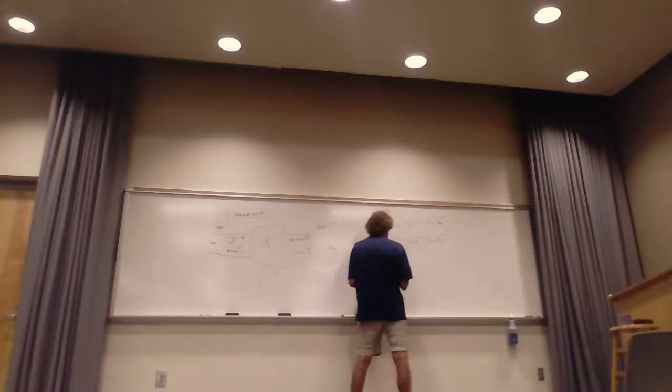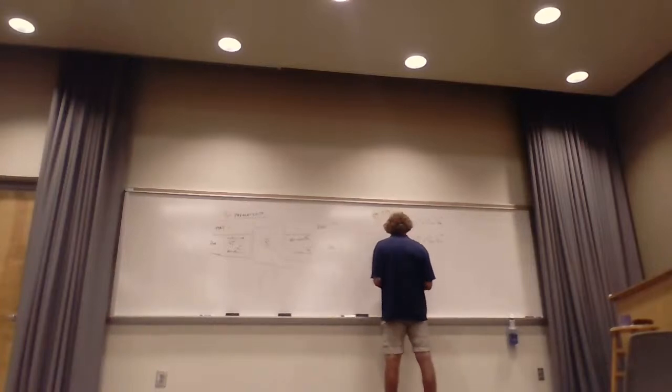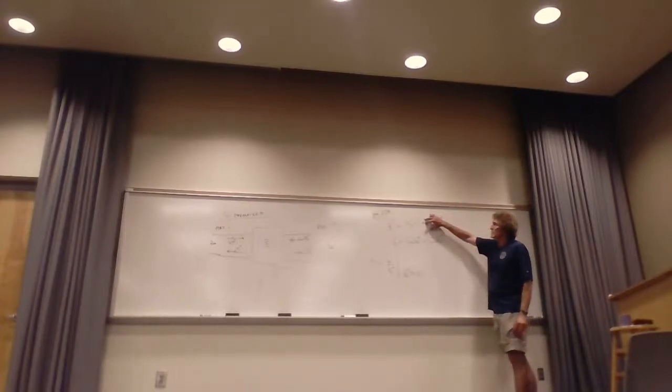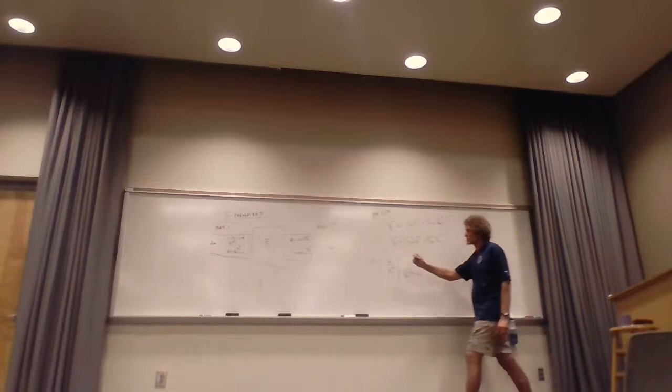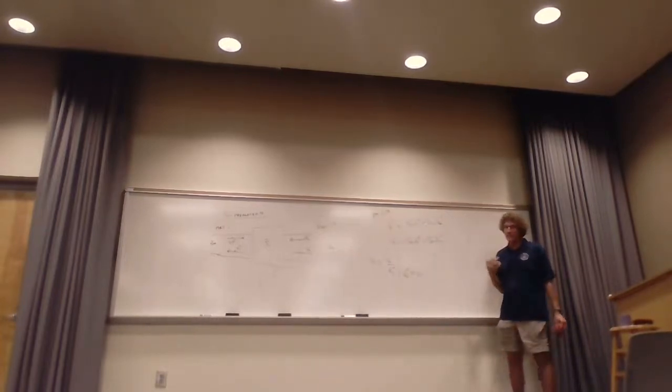Well, it's really a ratio of V1 minus over V1 plus, assuming that V2 plus is 0. If you look at this, if you ignore that, S11 is really V1 minus over V1 plus. If this is 0, in other words, there is no wave coming in here, so this component will have no effect.